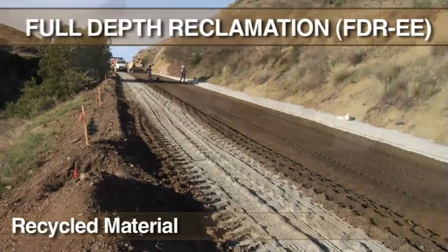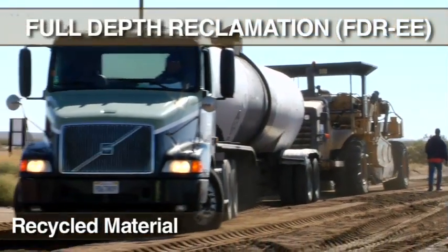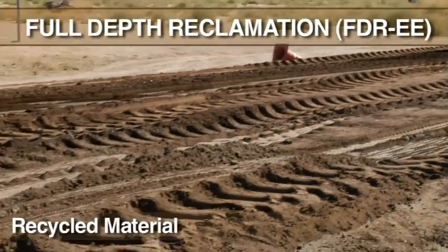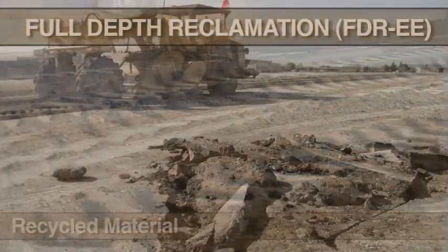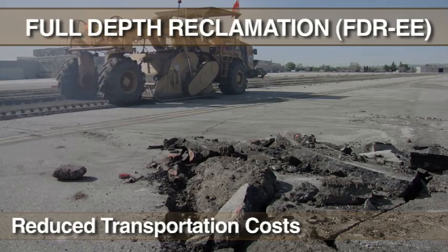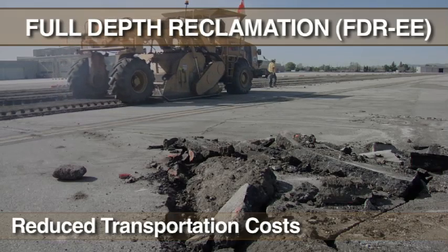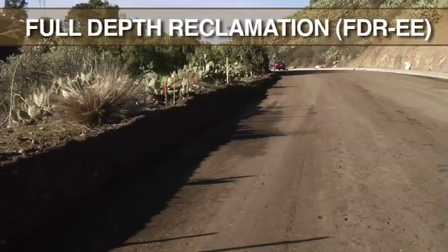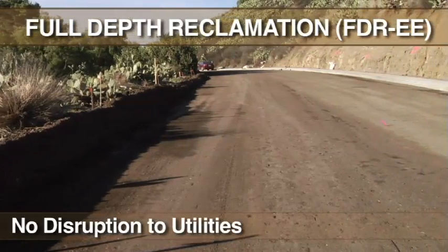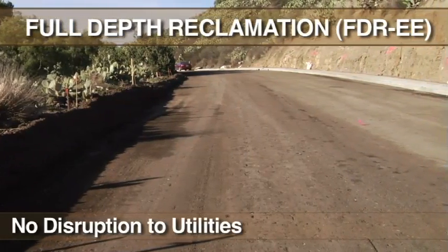A 25-ton truckload of engineered emulsion can, on average, eliminate the need to remove and import up to 60 dump truckloads of material. Transportation costs are reduced, since the existing roadbed is recycled in place and not hauled in and out of the job site. Utilities are typically not affected, since the FDR process is done in the confines of the existing roadway section.